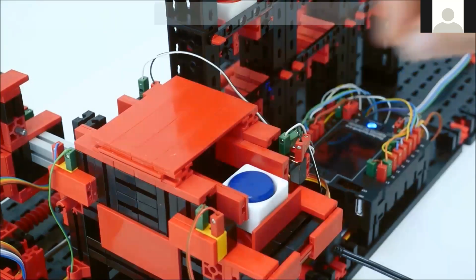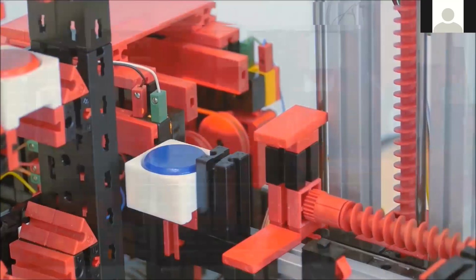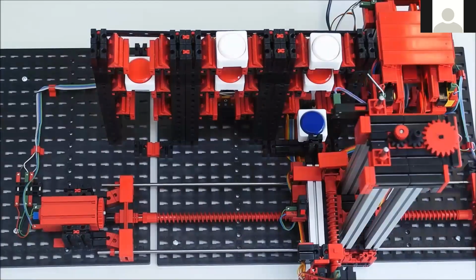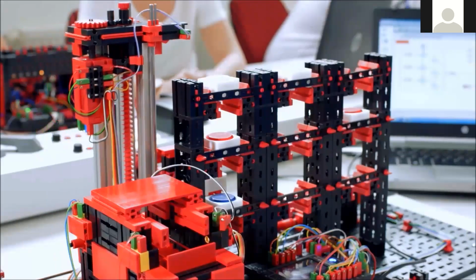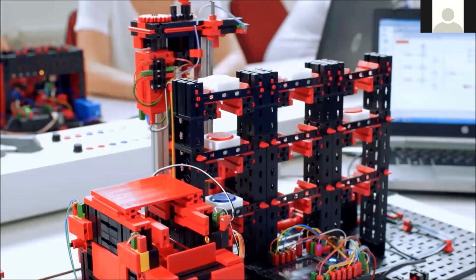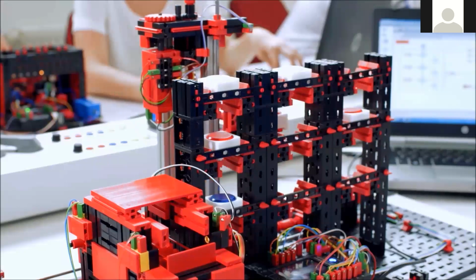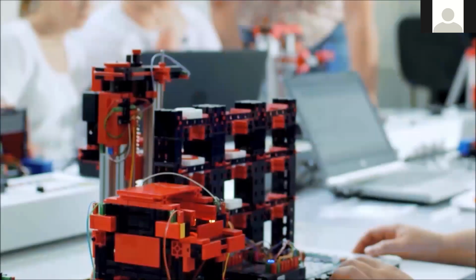approximately 18 pounds. Once again, the 24-volt version has a relay board for motor polarity reversal and both a multi-pin connector, again 34 pins with a grid of 2.54 millimeters, as well as additional PCB terminals with push-in connections for all inputs and outputs. Again, you will need to provide your own PLC and programming. And a limited edition 9-volt version is also available at this time, which again is pre-wired to a pre-programmed TXT controller, and again, one 120-volt power adapter is required.